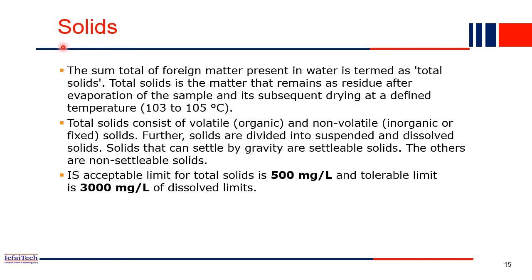Now the next is solids. Many solids will be present in water in a dissolved form, or they may be in a suspended form also. The total sum of foreign matter present in the water, we term total solids. Total solids is the matter that remains as a residue after evaporation of the sample, right? If you dry the sample, the water will evaporate, but the solids will be deposited at the bottom.